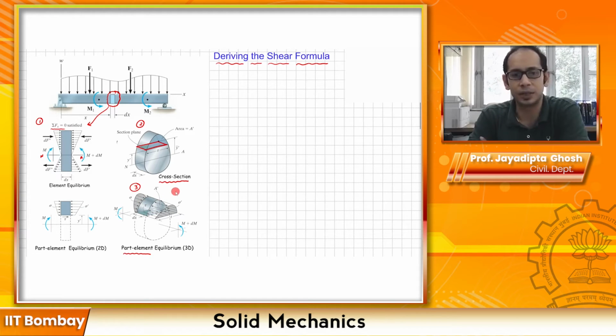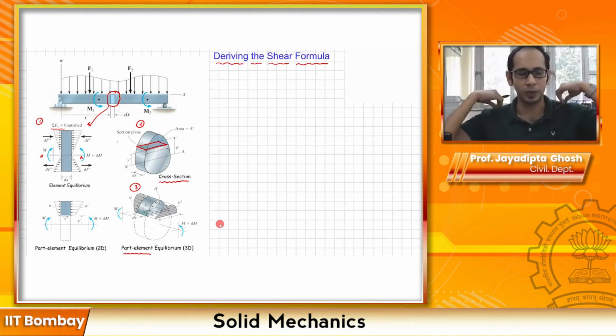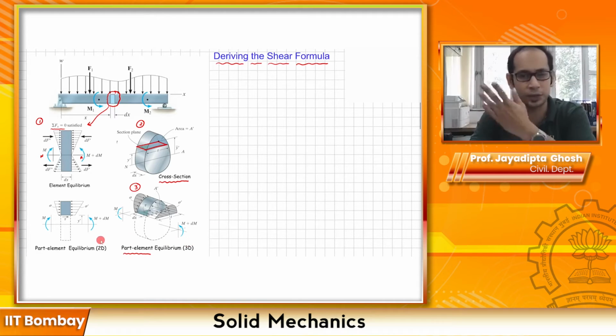So what is this additional force which is keeping this part element in equilibrium? Well, don't forget that across this face you had the transverse shear V which was acting, and in addition to that you also have this complementary tau. For this tau you have a complementary tau which is acting over here. So as you can see at the bottom face of this element, you have this stress tau acting. So we have sigma, sigma prime, and tau, and all of these are working together to keep your overall element in equilibrium. Okay, so this is the 3D figure. If you look at the 2D, just to make it simple, this is the 2D representation. This is tau, which is more clear in this figure. This is tau acting at the base over here, and the element length is again dx.